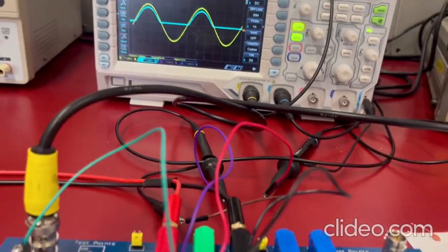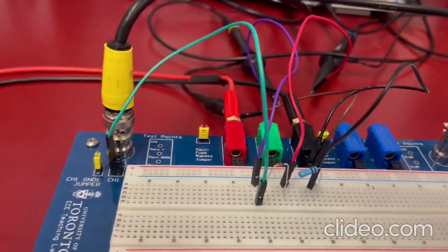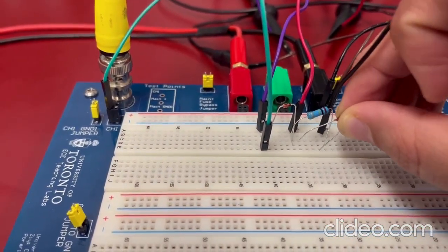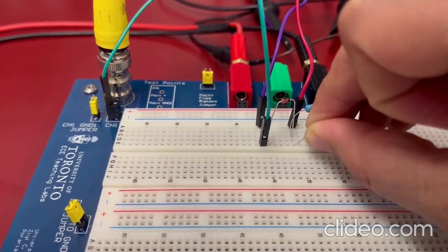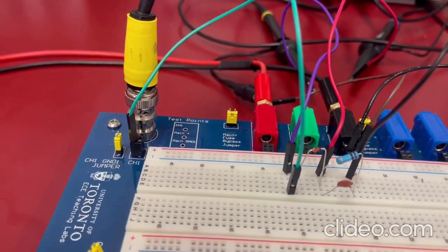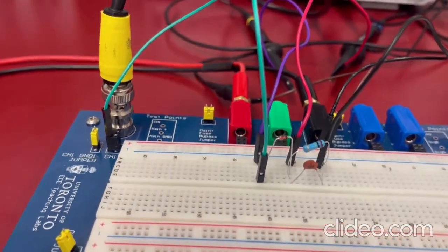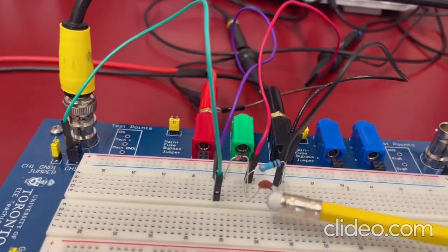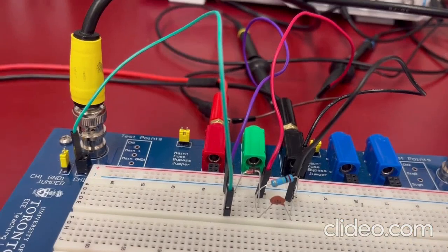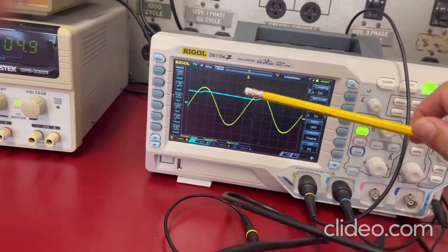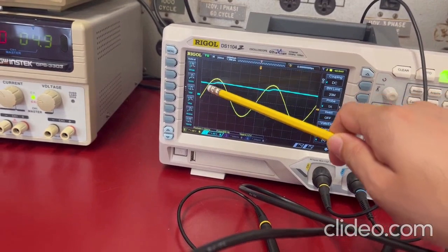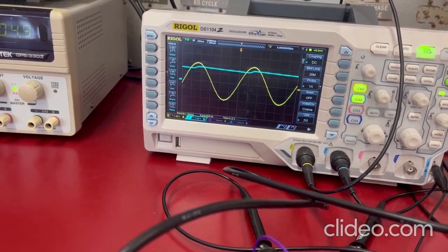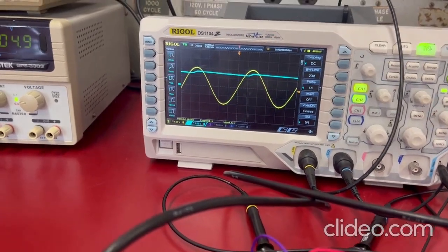In the E3 part, we are supposed to insert a capacitor between the diode output and the ground, which is in parallel with the resistance. So I have put a 100 nanofarad capacitor here, and you can see from my output here that now I'm able to hold the rectified output more, because the capacitor is charged and you get the rectified output like that. Thank you.